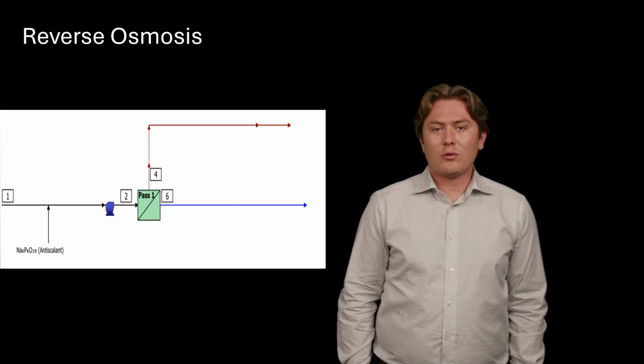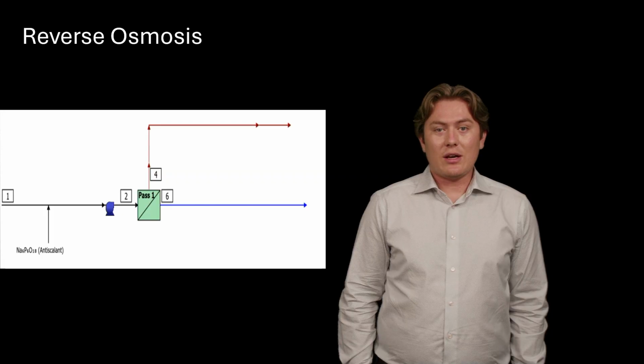The system uses spiral-wound thin film composite membranes, specifically the BW30HR440i, selected for its high membrane area, strong salt rejection, and suitability for brackish water. Overall, the RO unit enables effective water treatment and reuse within the system.